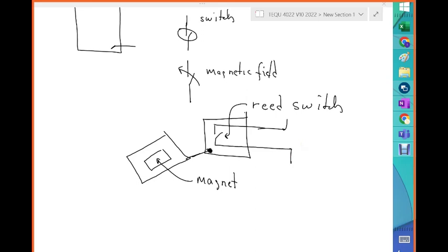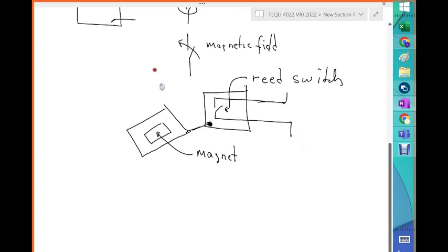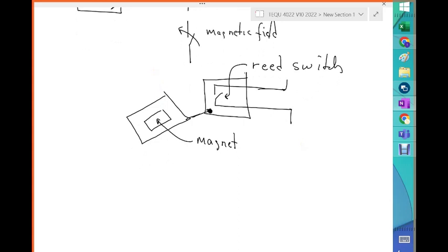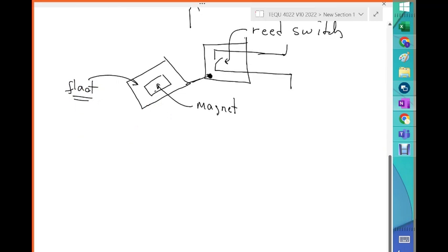There's nothing. Now, when the level starts to rise, what's going to happen is that this part, which is a float, remember the magnet is within a float. That's a float. It has a density below water density. So when you put this on water and the water starts to rise in a tank, for example, now you will have something similar to that,